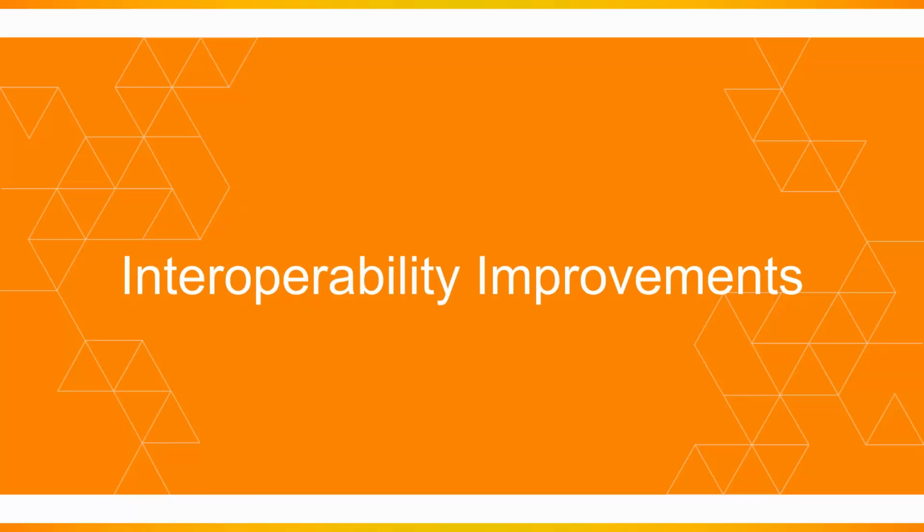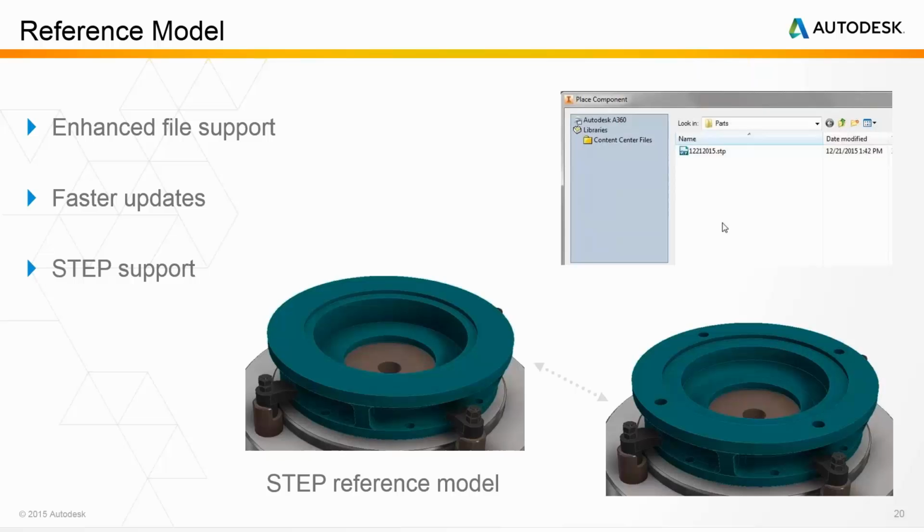And that becomes critical nowadays because we're often working in multi-CAD environments. And this is highlighted with the release of the AnyCAD technology. Now, AnyCAD technology became available in the 2016 release of Inventor. And it gives you the ability to work with non-native file formats and reference the data rather than convert this. Now, this is critical because rather than having to convert the data into an Inventor format and manage that file and have a second file to manage, you're actually referencing the original file. So you can check that data into Vault and manage it the same way you would, say, an Inventor file.